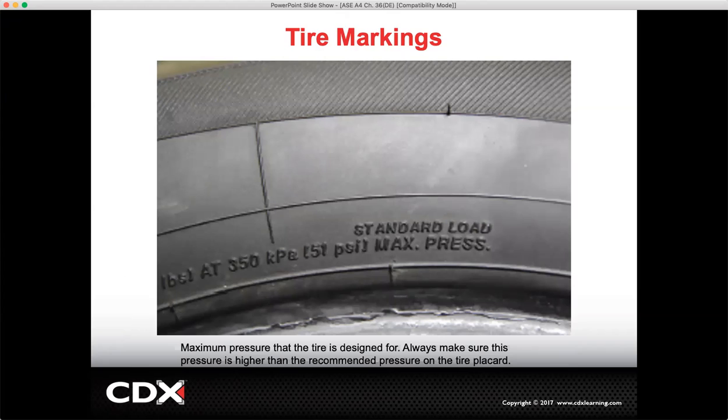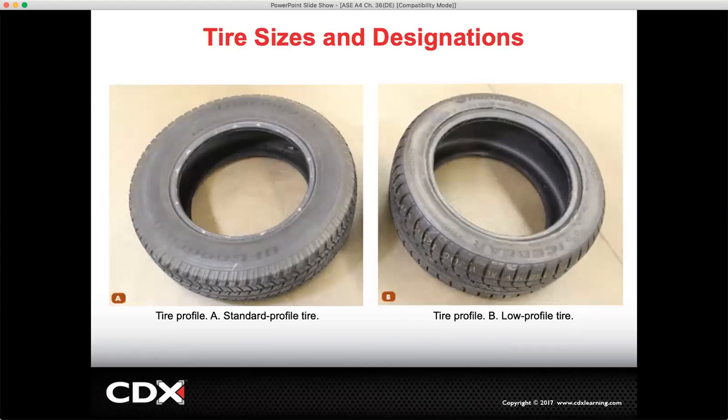They also need to have type of tire construction, the wheel diameter, speed rating designation, maximum air pressure, the load index, uniform tire quality grading, the UTQG system code, Department of Transportation compliance symbol, and serial number including date of manufacture code.